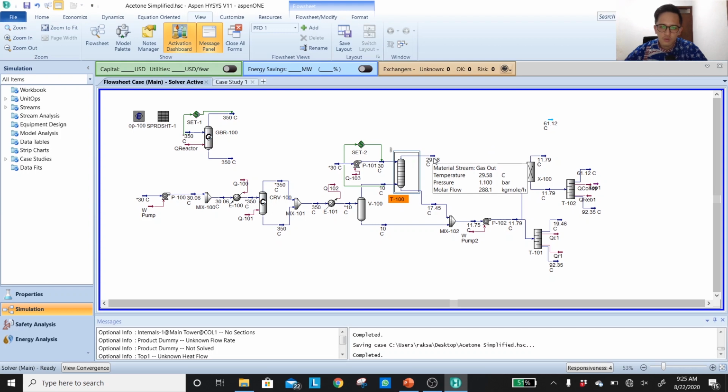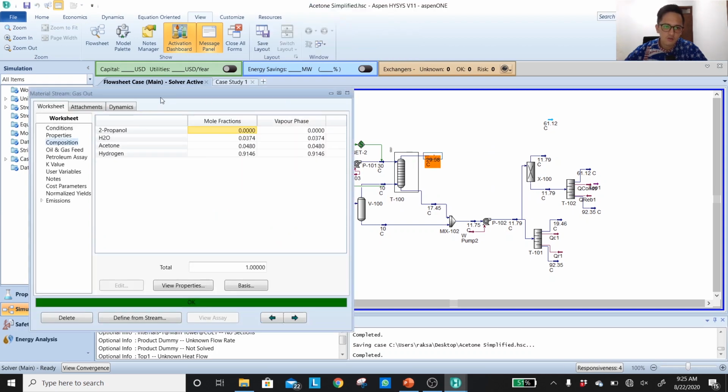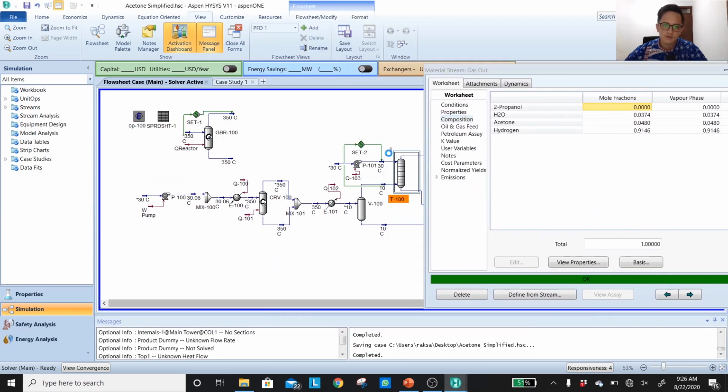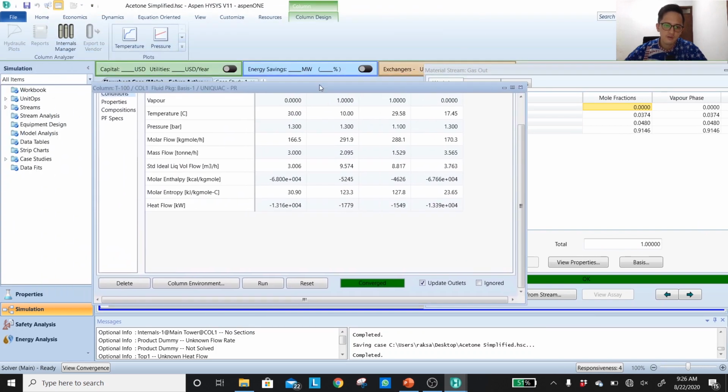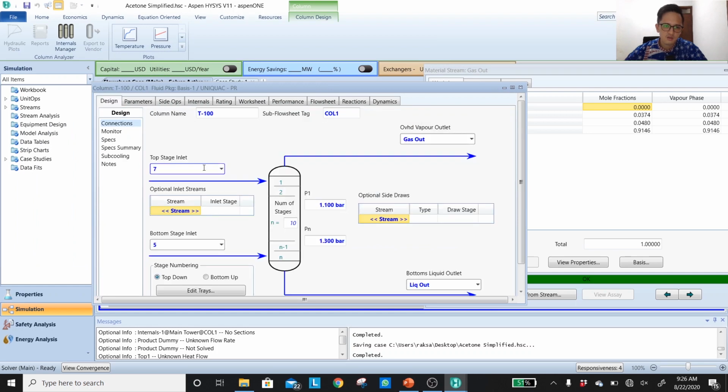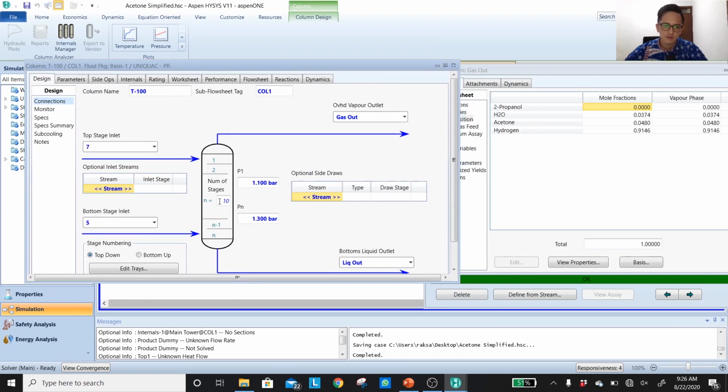To get a lower number of acetone loss, you can also play around with the amount of stages in the absorber. Okay, we haven't checked the results on that one. If it's only 10 stages, 10 stages is like 5 to 6 meter of column. It's quite small. The acetone loss would be at around 4.8%. So let's just try. If we double that amount, it's still doable: a column with 10 to 12 meter height with the same water inlet.